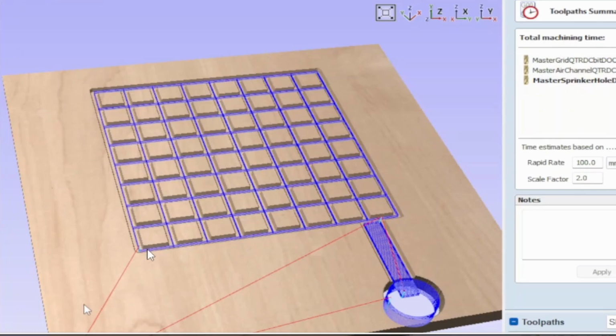That skill of creating a single vector for a grid is really nice, because if you ever want to put a gridded pattern on a spoil board with a VCarve bit for measurement purposes, this is going to be very transferable. So even if you're not going to make a vacuum table, you probably want to see at least this grid portion. It's a great little skill to have.